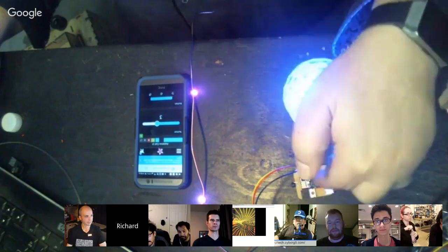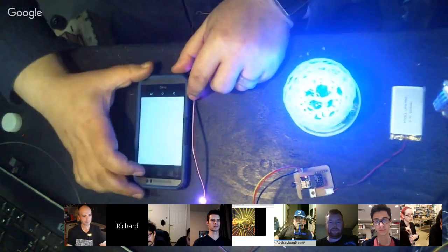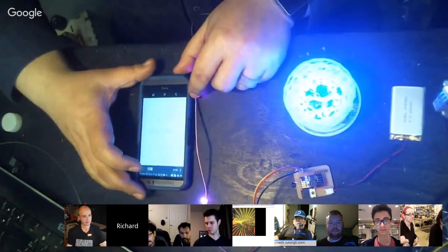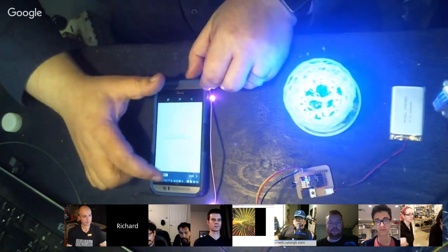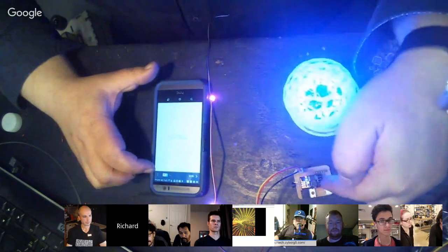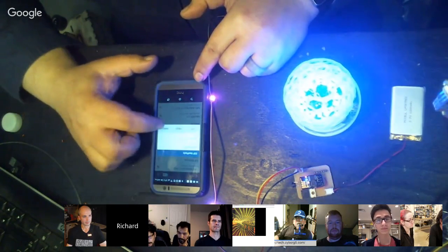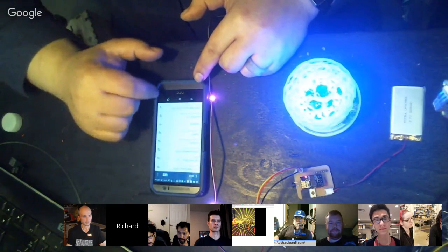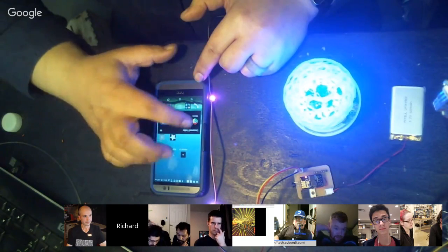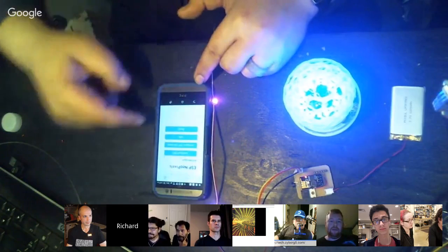So in order to connect this to the network, I can disconnect from my Wi-Fi here at the makerspace, and on my phone, it's actually going to pop up with the SSID for this chip as a host. So ESP NeoPixels, I hit connect, and now I can go to my web browser. And if I go to home, you can see now there's a configure.